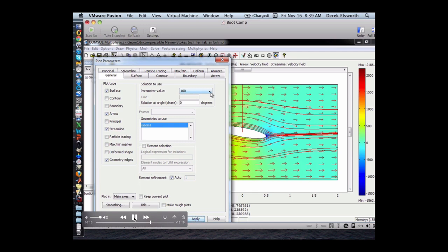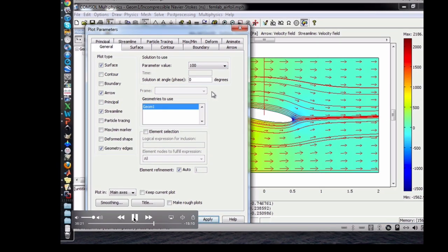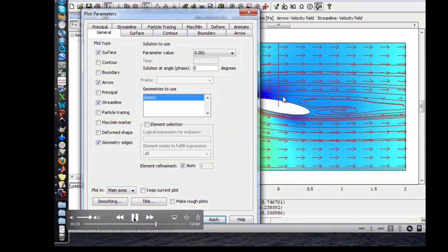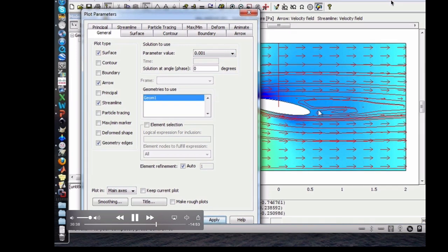Reynolds number of 100. And you see that this flow field nicely hugs the back of this and then just goes off linearly. We'd expect the resulting drag force from that to be mainly viscous. If we look at the highest Reynolds number, so this would be 10 to the 3, Reynolds number of 1,000, you see you get this separation at the back and this wake all coming in. And so the net result of this is that you have different flow fields, and therefore if you do the calculation to figure out exactly what we did by hand to calculate what the influences of pressure and shear stress are on the drag force, you'd end up with different magnitudes.